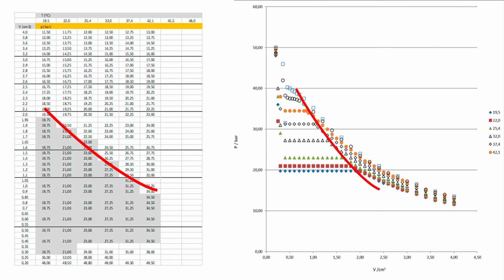In the same way, on the left side, we can observe the different states of the saturated liquid. These states, of different volume, density, pressure and temperature, have in common that they are the states of the fluid in which the first gas bubble appears in the heart of the liquid. By means of an isoline, we can link these representative points. In the states in which we have not taken a measurement, this curve offers a prediction of its approximated situation.